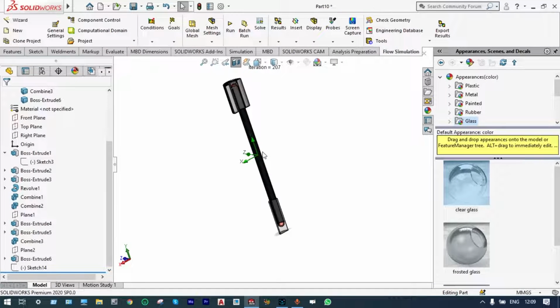Okay, this is all about our today's analysis. In this analysis, we got the temperature at different zones of the heat pipe, that is the temperature at the condenser zone, evaporator zone and adiabatic zone. It is having high thermal conductivity compared to normal pipes. So in the reverse way, you can say that the effective thermal resistance of a heat pipe is very less compared to normal copper. So it will be working as a very good thermal conductor. And again, to have better efficiency, we can change the orientation of this heat pipe. When the orientation is between 22 to 45 degrees, in that case we can have maximum temperature at different surfaces of condenser, evaporator and adiabatic zone.